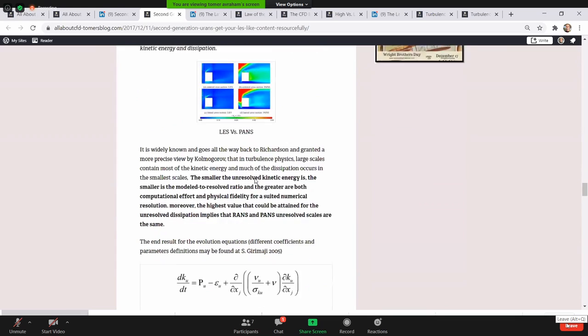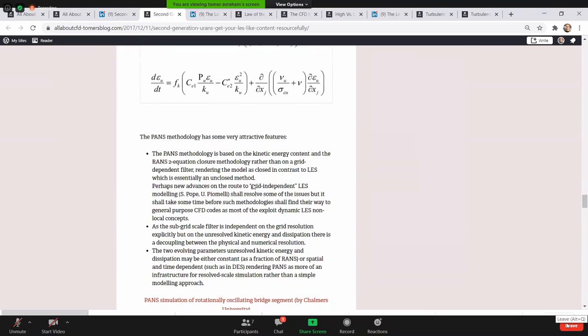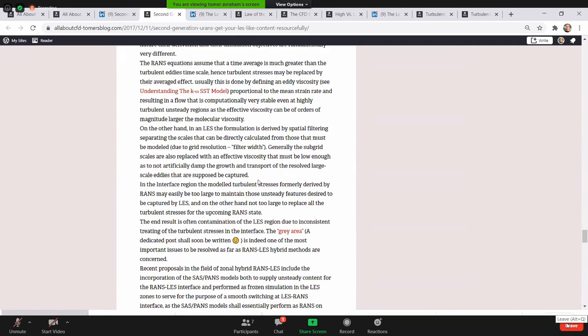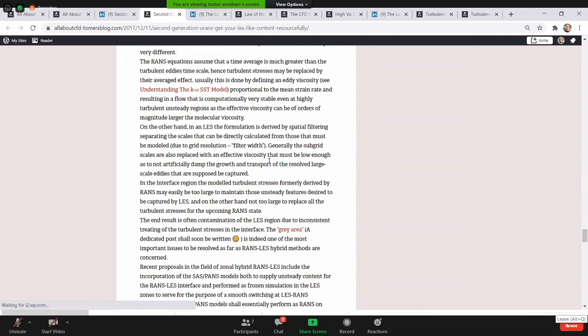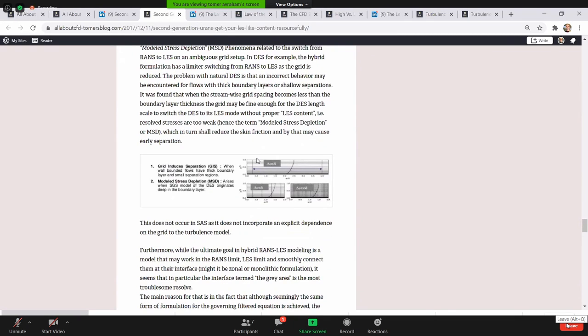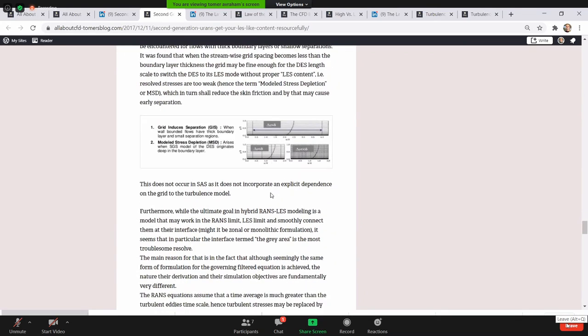But we're still not there. Still not there. And the near wall area has demands like for large eddy simulation, like DNS almost. You can stretch the cells, you need to get to the Kolmogorov scales, and it's not possible.